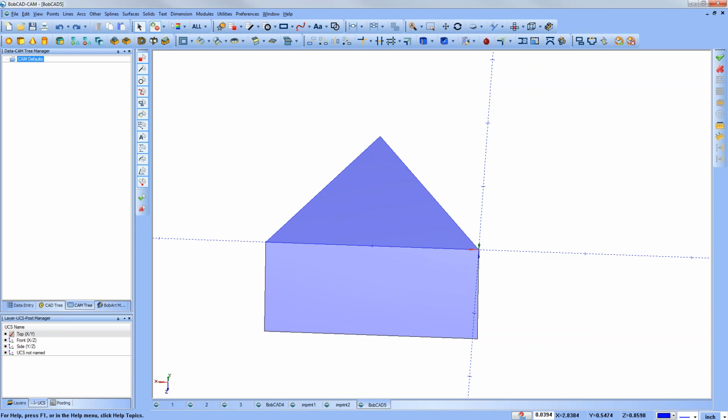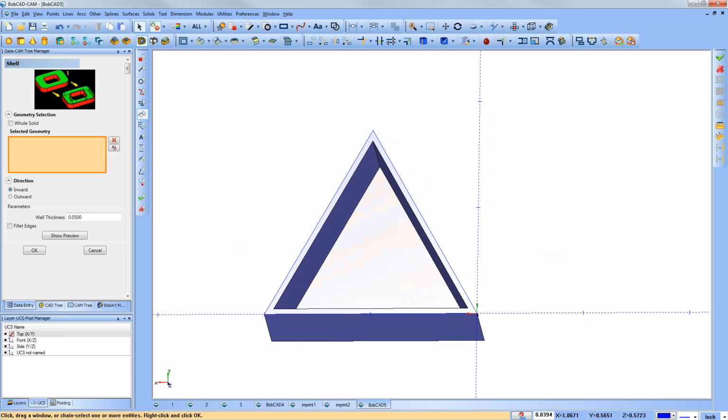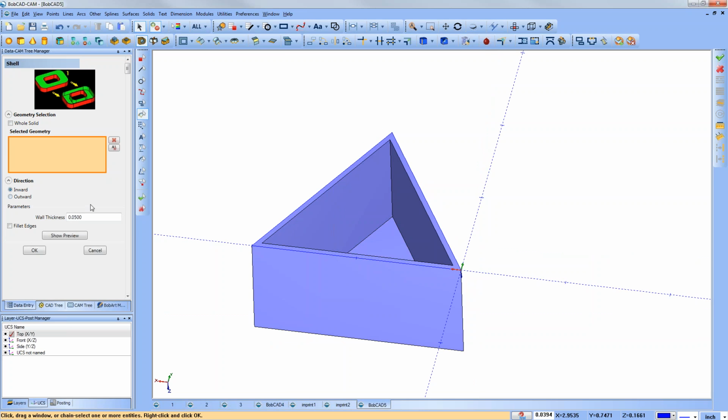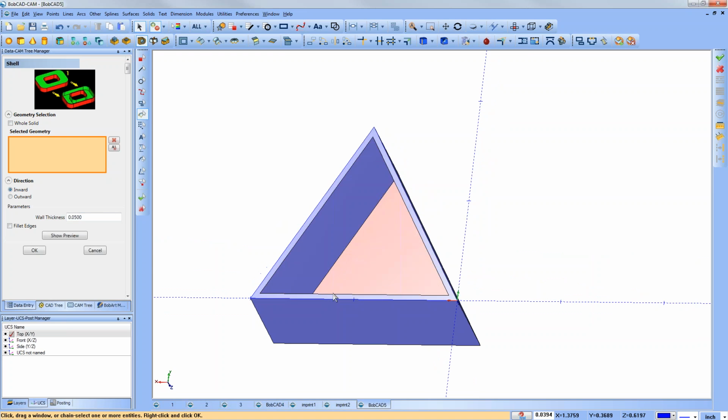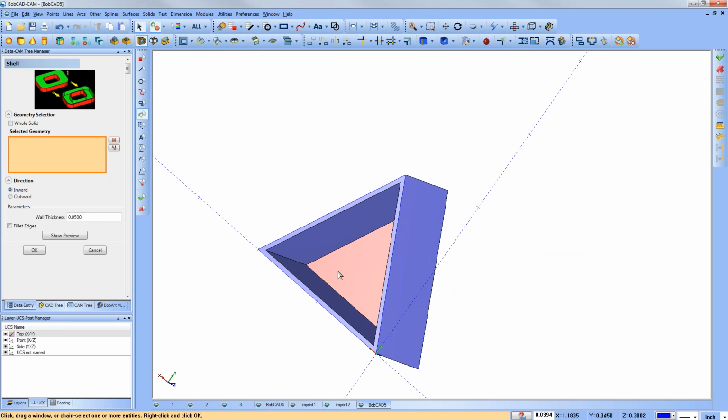Mark was asking, where was the depth set? Mark, the depth isn't set. It's just a thickness from the shell. So it's not necessarily a depth, it's a wall thickness that's consistent around the part. All of these walls and this floor, which is also considered a wall, right? All of this is going to be the 0.05 or whatever number you set in there.